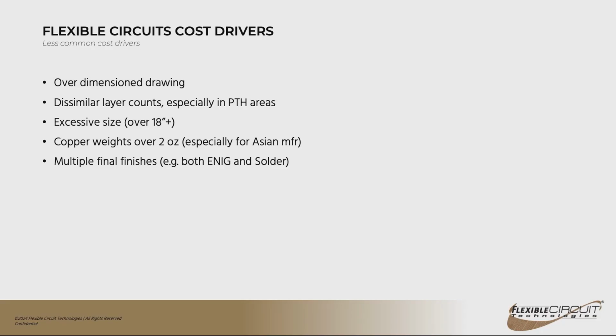So when you have a large circuit, it could affect the yields. We can certainly assemble those components to flex. We do 01005 components all the time. So that's about as small as they get. And we don't have any problems with that. But on very, very large circuits, the larger the circuit is, the more difficult it is going to be for us to define the small features on the flex itself. So it could have some impact on the yields.